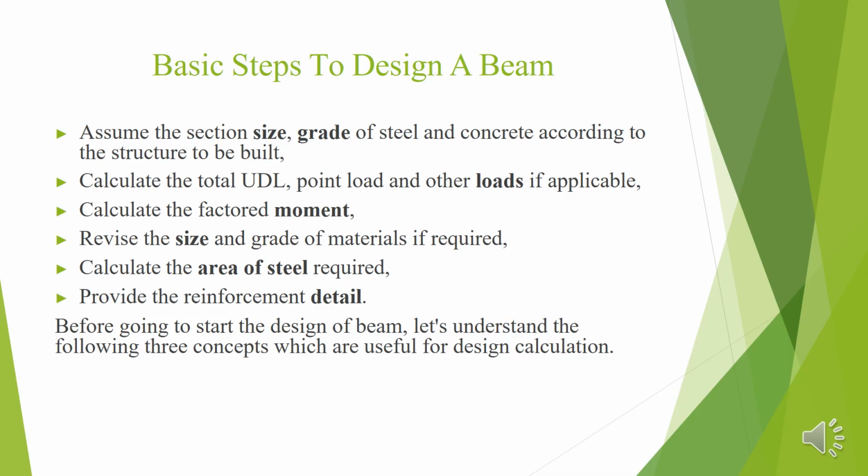From this factored load you have to calculate the factored moment. This factored moment will give you ideas about the moment and shear force acting on your building. So for this we have to revise the size. There are formulas given in IS 456 to calculate the depth required according to the moment acting on the structure. Using this we can resize the structure and grade of materials if required. If the depth provided is not enough, we can increase it. If the grade of the material provided is not enough, we can increase it.